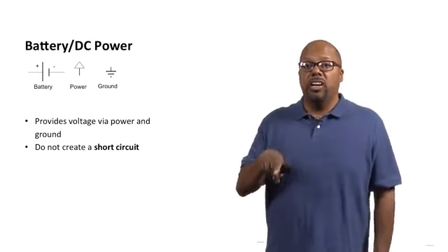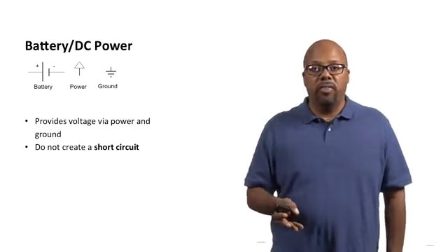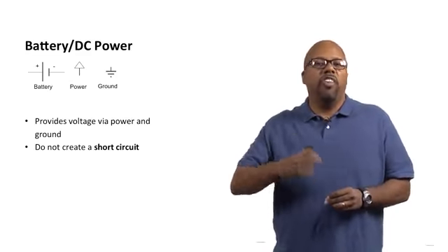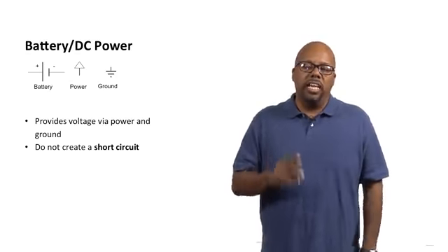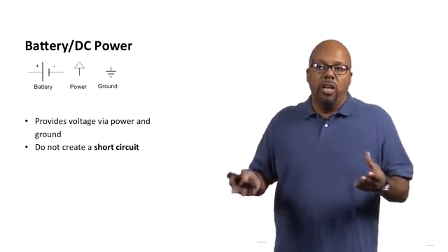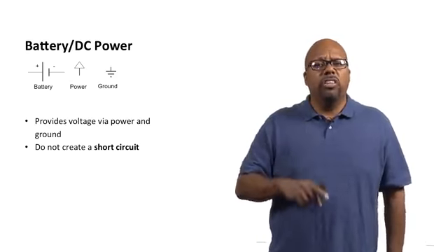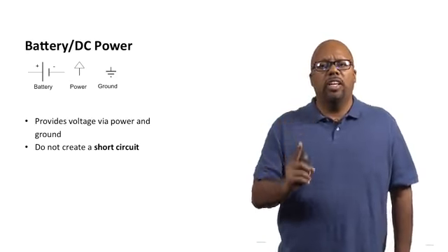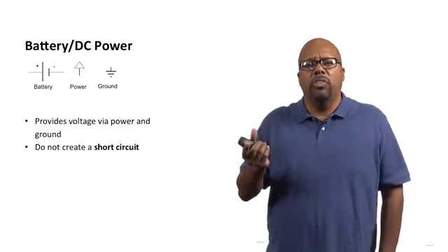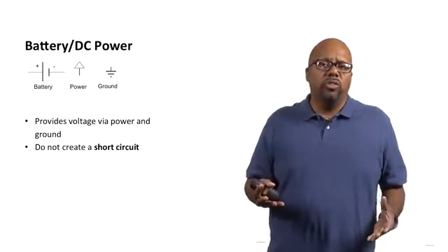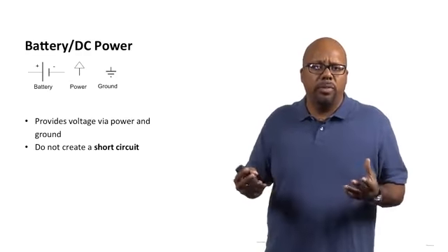For instance, in all of our examples, we're not using a battery. We're using the Arduino itself, right? We're going to pull 5 volts and ground from the Arduino itself, so we won't use a battery. Instead, we'll just have a power symbol and a ground symbol on our diagram. Power is actually drawn several different ways, but we're going to use a little triangle that points up like that. That's usually power, and next to it you would have the voltage value. For instance, if it was a 5-volt source, you'd have the little triangle, and next to it you'd write +5V, something like that.